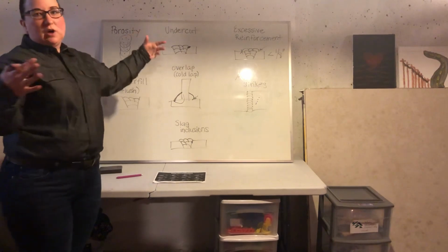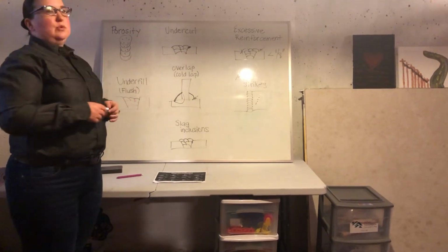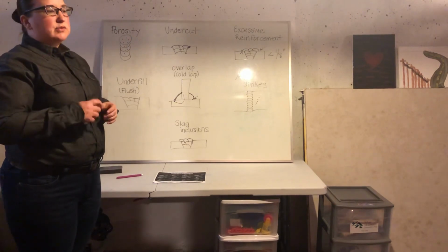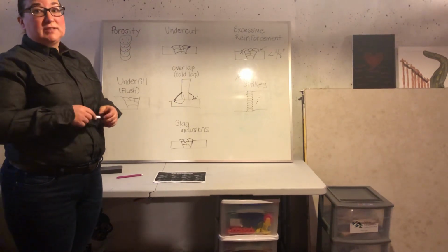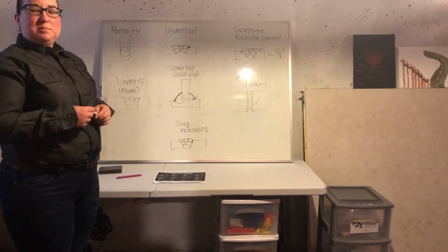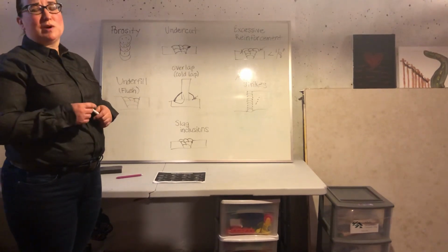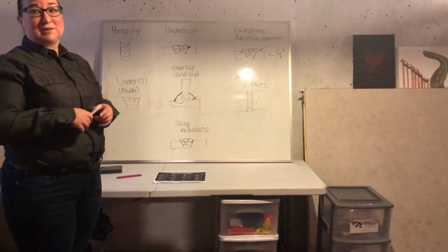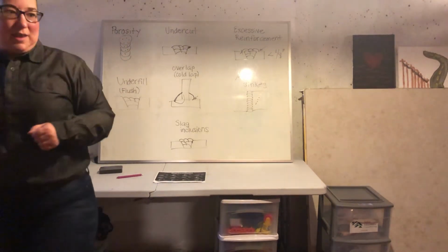And then what's not seen through a visual weld test is going to be seen through your destructive bend test. So those discontinuities really come to light when we start putting some stress on that weld metal. So we all aim for that nice pretty bead. Nobody wants to paint over or grind our welds. We really want to be proud of the finished product that we put out there. So good luck, guys, and aim for perfection.